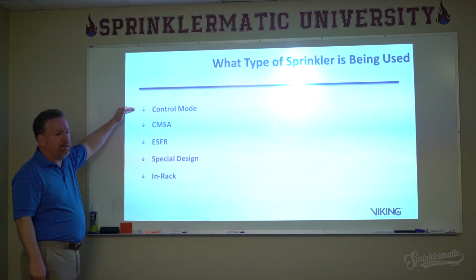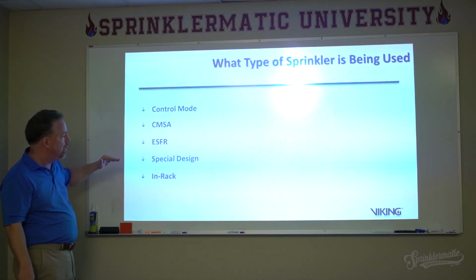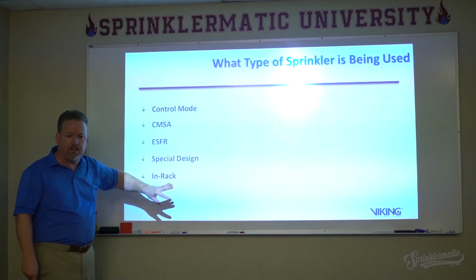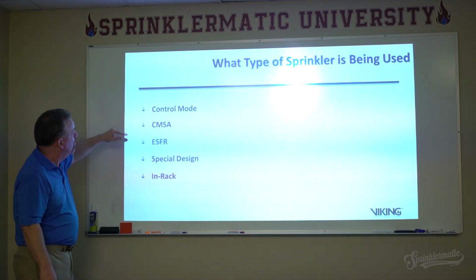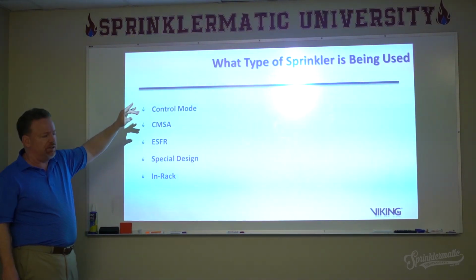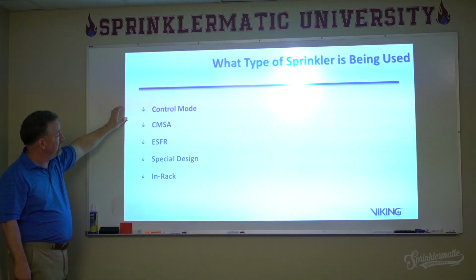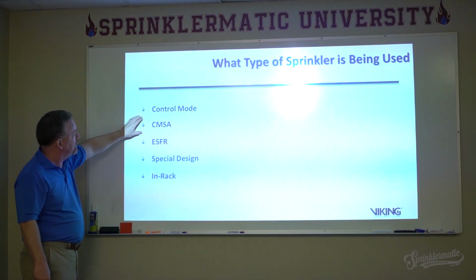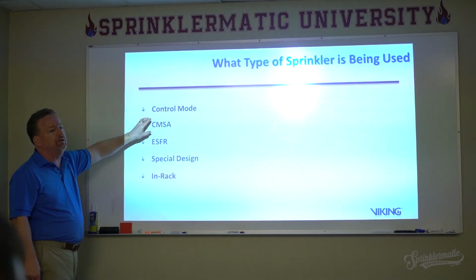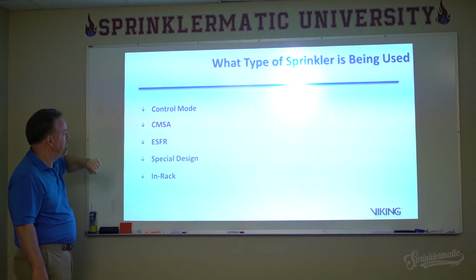We pick a sprinkler based on the designer looking at that and saying, in consulting with the owner, maybe with the AHJ, but ultimately it's the designer, the engineer's final decision: what type of sprinkler am I going to use? Am I going to use a control mode sprinkler, a standard spray control mode sprinkler, or maybe a larger orifice control mode sprinkler? Am I going to use what we call a CMSA? CMSA means control mode specific application.